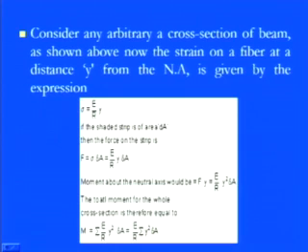Now, if I want to compute this moment for the whole section, because till now we have discussed a small strip with elemental area dA and strip width dy, then for that strip the moment is E by R y square into del A.